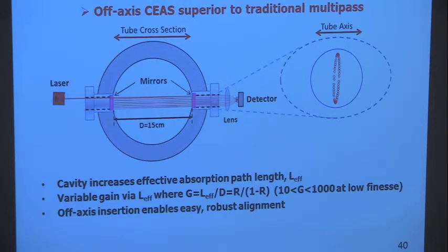We had to deal with this cavity noise problem. And in doing this, we found out that this alignment was really easy. But you have to buy these mirrors. And if you buy a mirror that's designed to be 0.99 reflectivity at your wavelength, it won't be 0.99 at other wavelengths. So you have to buy these mirrors, and they might cost $3,000, $4,000, $5,000. Then the question is, how long are they going to last inside the shock tube with all the stuff that's in there? But we tried it, and it's pretty good. It's not perfect. In fact, most mirrors have held up. Some mirrors, after 6-9 months, we've had to replace.